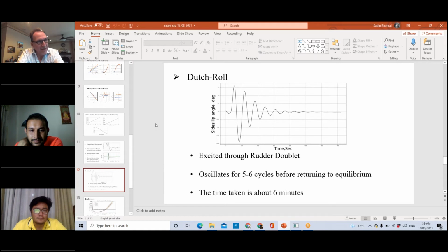I mean, a long time ago, I experimented with a landing gear that just had a little spring to retract it. But I rigged the gear forward, so it was sitting on the ground. The weight held the gear extended against a stop. Then after I lifted off, it just automatically retracted. No servos, no nothing. It was just spring-loaded. And in this case, when you come in for landing, it'd be kind of nice to let the nose go to the ground and just come to a stop instead of touching the nose wheel and bouncing back up. It might be pretty nice to derotate the airplane. So depending upon where the turret is and so forth, that might be a kind of fun, easy, low-cost trick we could do.